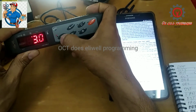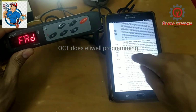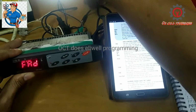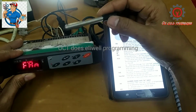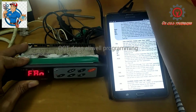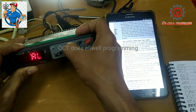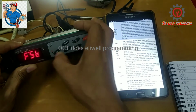Okay, then I'm going to set it to memorize. Now this one will, just in case this room sensor is malfunctioning, this evaporator will stop upon reaching the value of 15 degrees, which I put to the FSD.